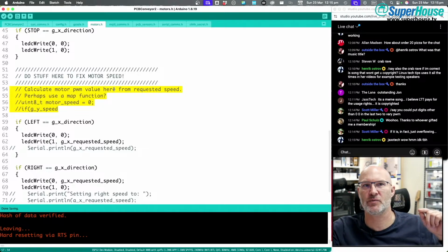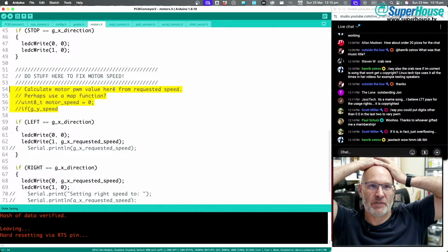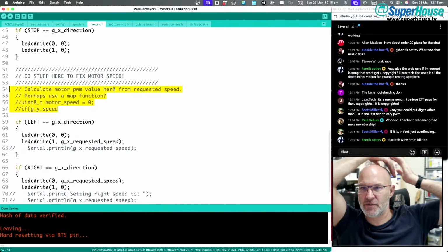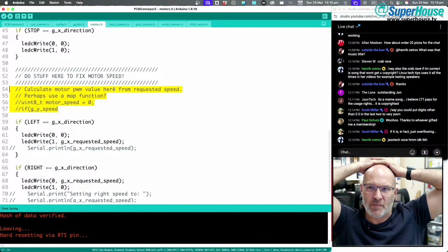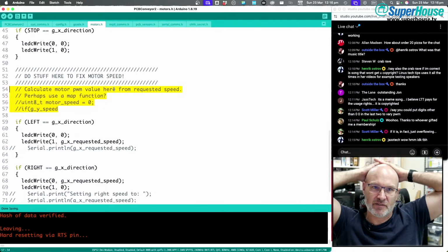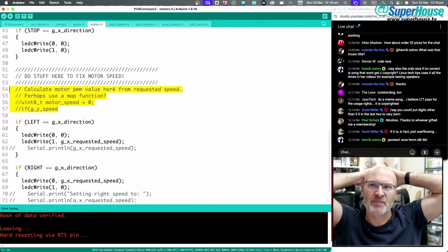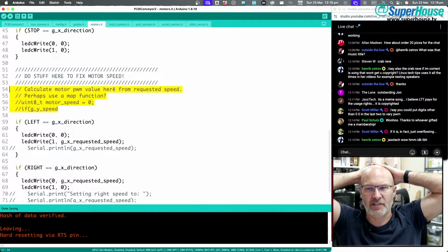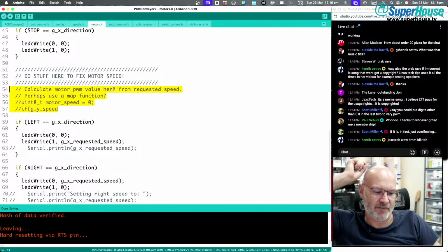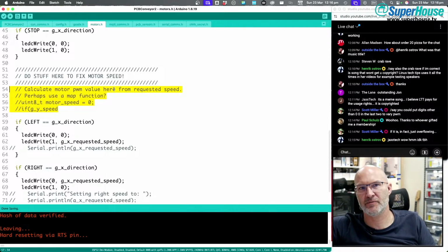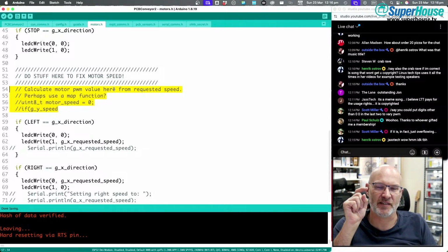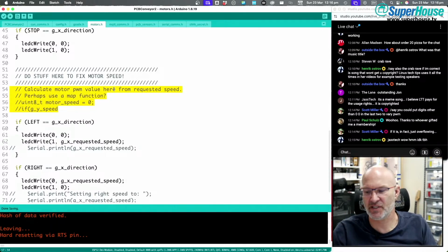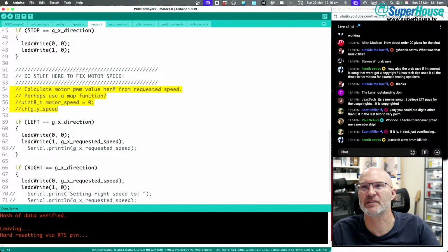So what I would do is have the actual belt on it and a mark on the belt and time how long it takes to move a certain distance, or I could do it by using an RPM sensor to measure rotations of the wheel, and based on the 50.65 or whatever it was ratio, I could then, because of the radius of the drive wheel, back calculate from the linear rate of movement what RPM I need to achieve the correct linear movement, and tune it that way. So either way would work.